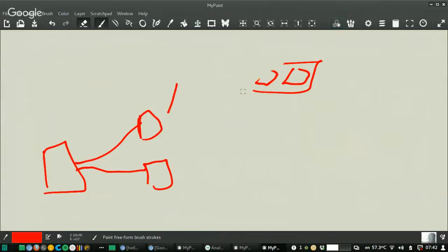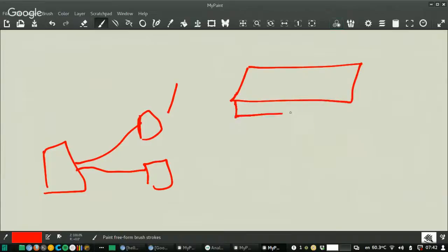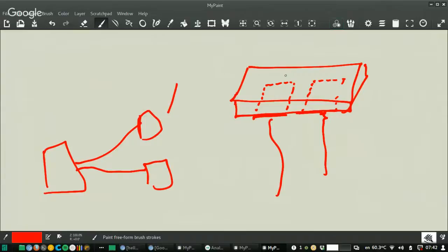Let me draw this again. Under a piece of acrylic, so you cut or you get some piece of acrylic spare, and underneath of this you put these copper things and you solder wires to this, and you experiment putting your finger on top of this, and also set a threshold so when you are near this it detects that you are touching.